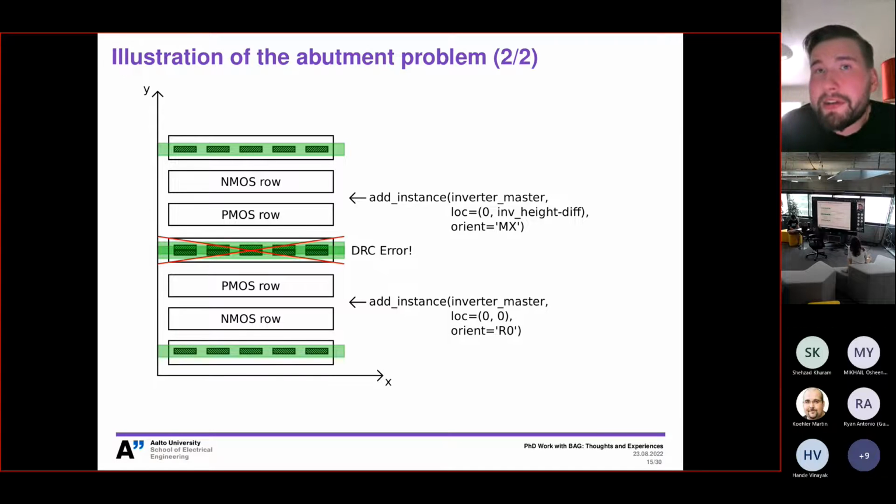No, I'm not saying that you can't. What I said is that you truly have to take care that your substrate width and the parameter that controls the spacing here are such that the sum of those two is divisible by the track pitch. That way you can overlap the substrates.